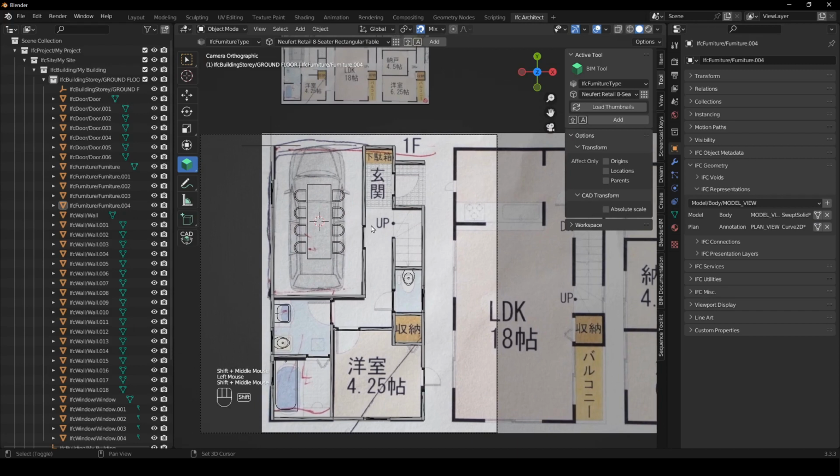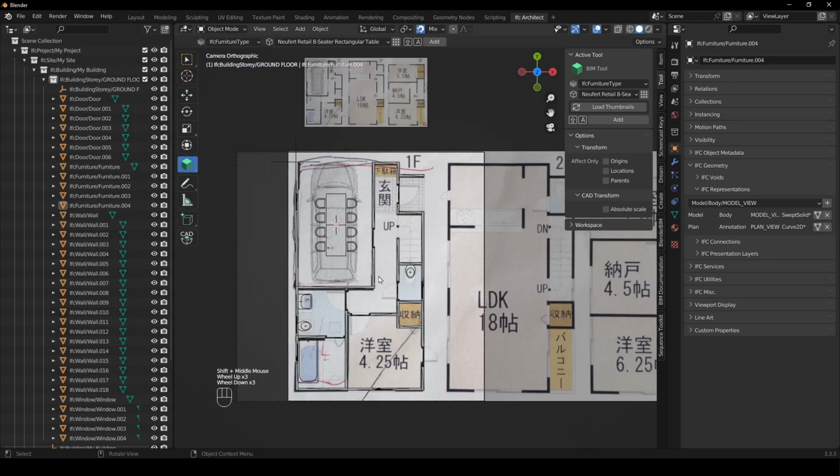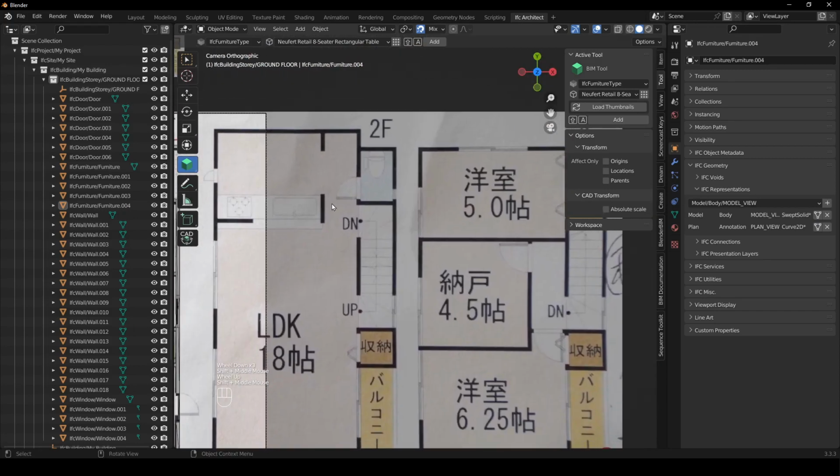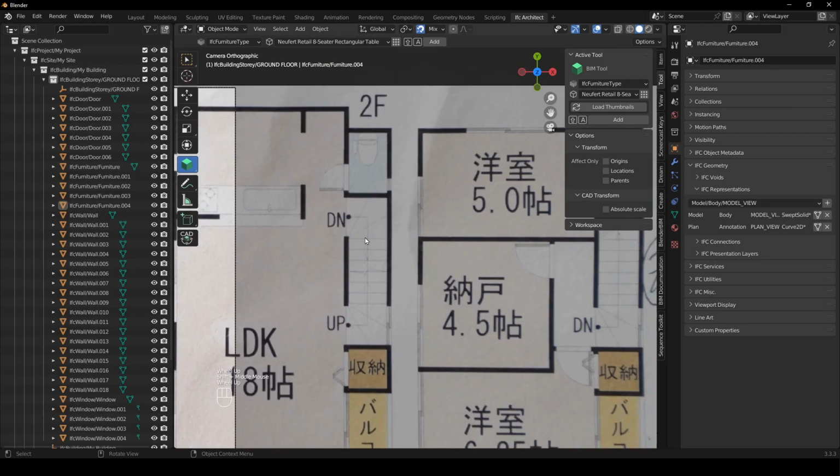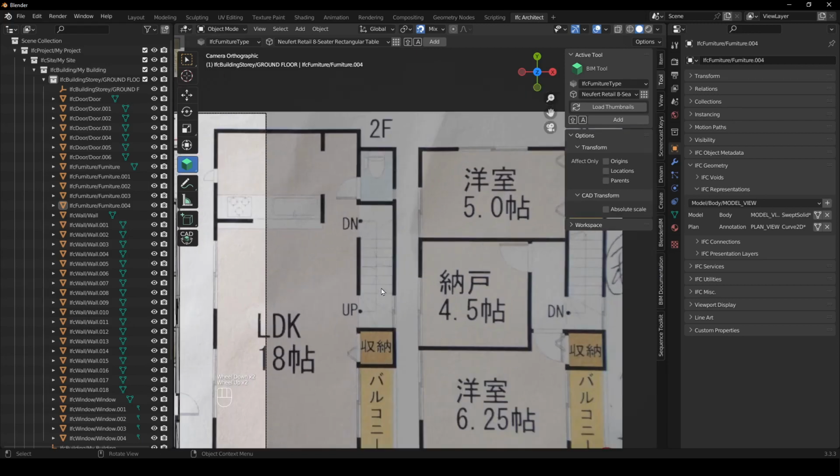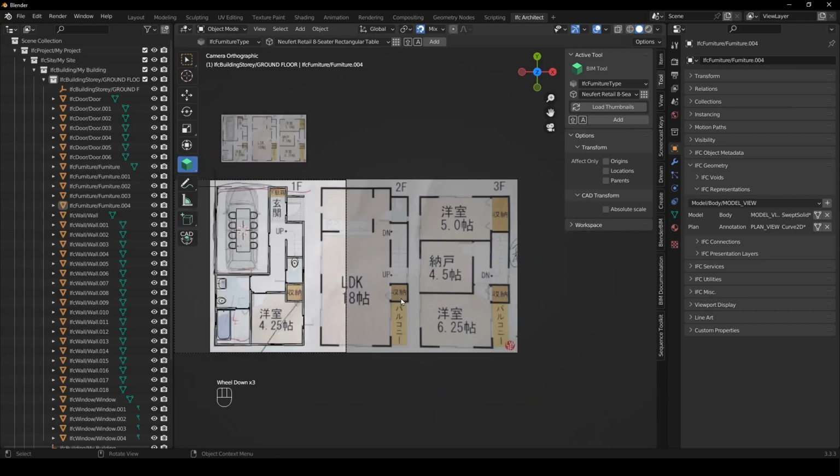Okay, cool. And then the next thing we want to do is these stairs. You can actually see it a bit clearer on the first floor, here, the 2F view. So there's 1, 2, 3 winder stairs, and there's 1, 2, 3, 4, 5, 6 intermediary stairs, and 1, 2, 3 winders, and then the last is the step for the slab as well. So there's 13 steps altogether. And how I've worked it out is at a step height of 185. So it works out to 2405 millimeters for the height.